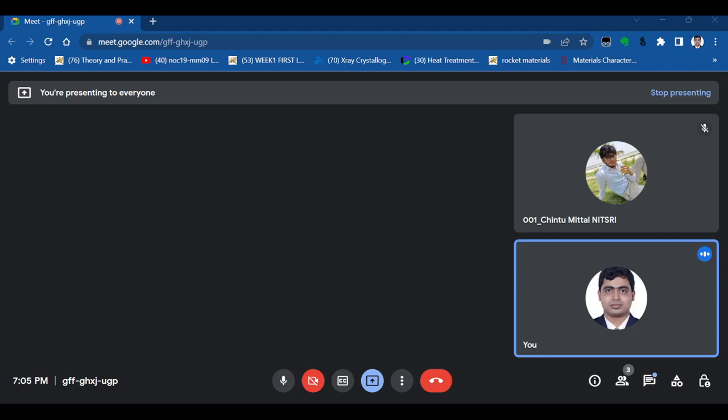And what will be the fraction of solid for the same 47 weight percent alloy? When you have to take the fraction of solid, you have to go this side. This AB divided by this whole length AD. Okay, if you have to calculate fraction of liquid, you take the opposite direction. If you calculate the fraction of solid, then you go in the opposite direction. So for liquid, we calculated BD divided by AD. For solid, we calculated AB divided by AD.